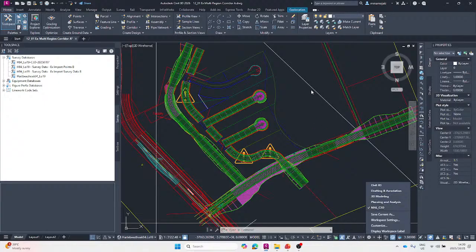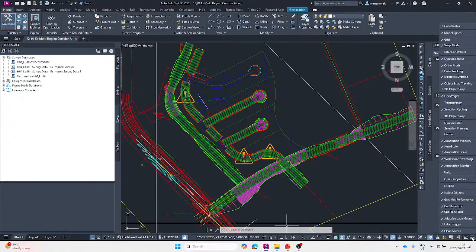So a customized workspace also entails the different properties that you see either on the left hand side or the right hand side, and then your status bar as well. That is everything that you see over there: your drawing, your annotation scale, your drawing layout, your coordinates, and then your snap tools. Over there you can change your snapping settings as well if need be. So these are your status bar items that you can simply change.